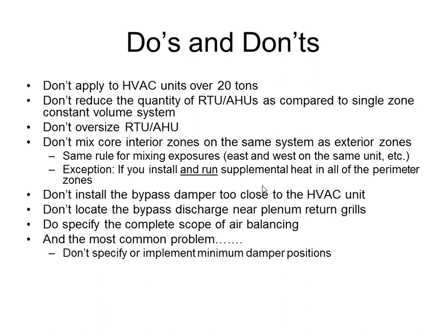Real quick, we're just going to go over, I guess, a summary of what the do's and don'ts for VVT systems, and then I'm going to show you a VVT system that we put in, and then we're going to go over some questions. So, some don'ts right off the bat. You do not want to do a VVT system over 20 tons. Usually, applications that size would require a cooling all the time load, so you'd want to go with VAV.